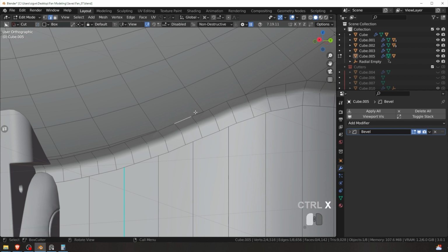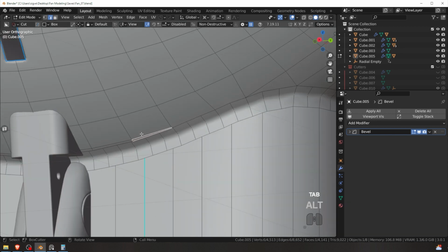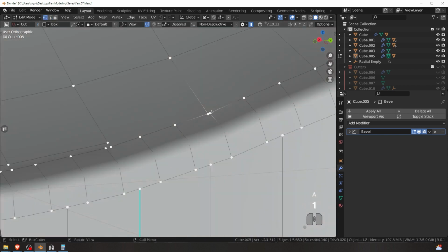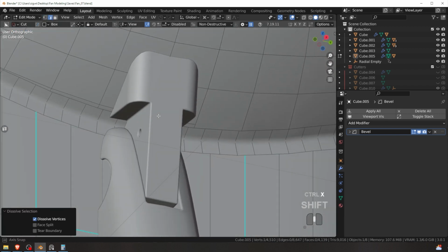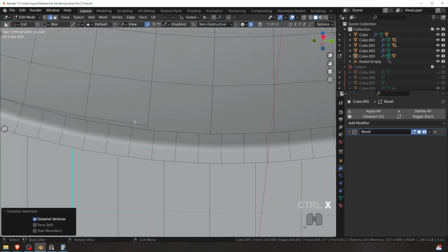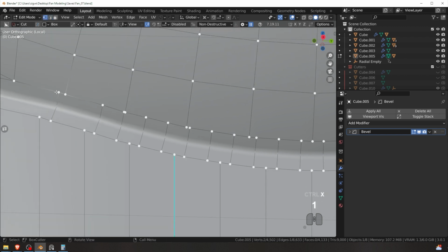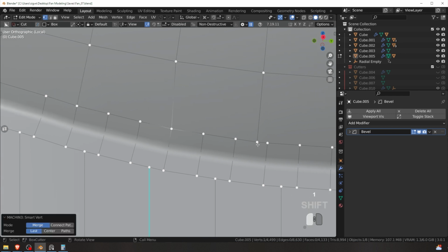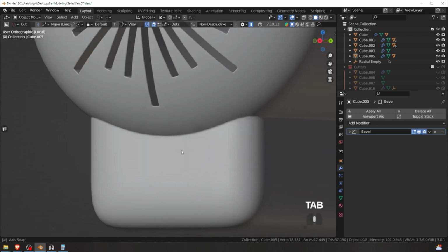For this one, I'll just dissolve these two, join this to this one, this one just like that. I'll also run the cleanup with 3, and let's see here, this one again. This whole edge loop actually, I'll just isolate this so you can see this whole edge loop actually shouldn't be here at all. It's just making everything worse. That's near missed edges. Let's just join them. That's fine. Okay, there we go.